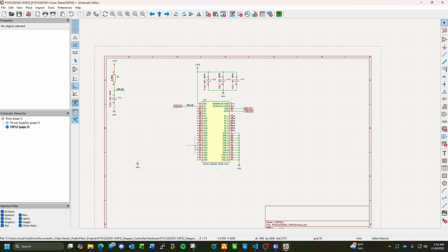In my opinion, I actually prefer it because when you're troubleshooting schematics, the hardest thing to read is when so much is bunched onto a single sheet. You're just trying to separate everything, and it becomes an absolute pile of unreadable garbage. I do not like that. It makes it very difficult. So if you've got to add extra sheets just to manage and mitigate, to make it more human readable, to make more sense, to have a more logical flow, do that. It's going to make your life a lot easier in the long run, especially when it comes down to troubleshooting.